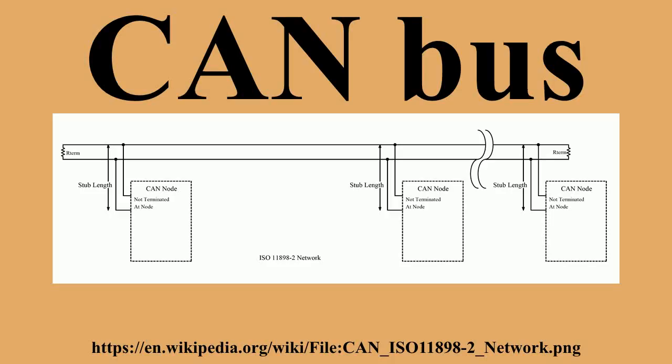Synchronization is important during arbitration since the nodes in arbitration must be able to see both the transmitted data and the other node's transmitted data at the same time. Synchronization is also important to ensure that variations in oscillator timing between nodes do not cause errors.